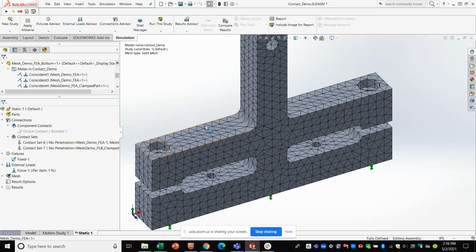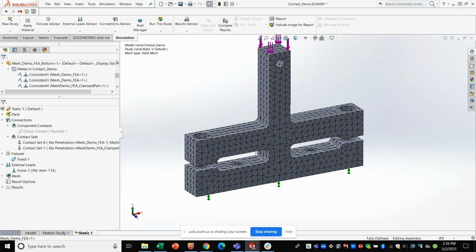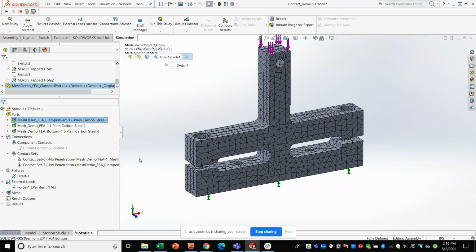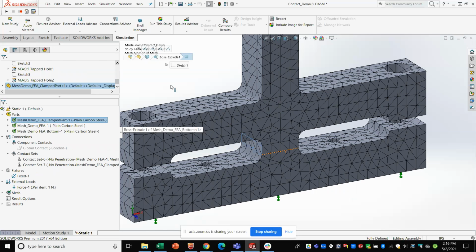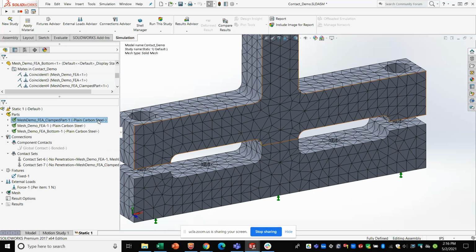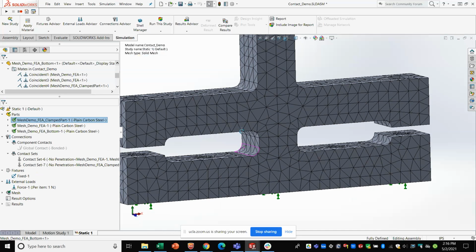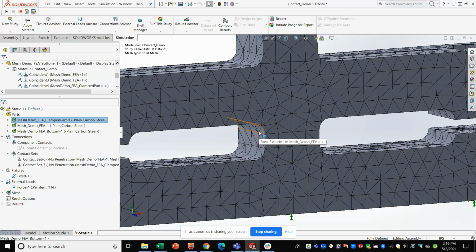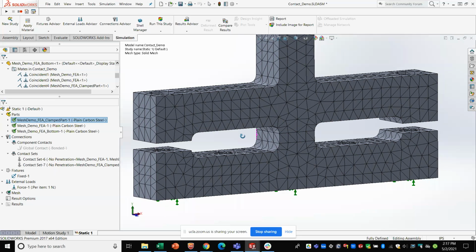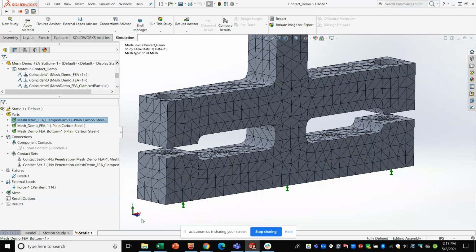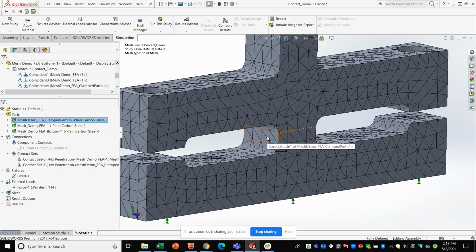And in the case of the part being sandwiched, it is actually not constrained in any direction. It's got a potential sandwiching in the y-axis, but any microscopic imbalance of force in the z-axis or the x-axis will cause it to fly off to infinity because it's not constrained in those directions.